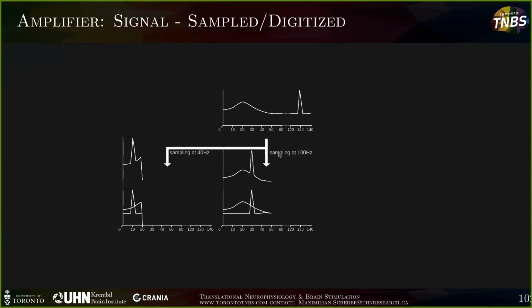So let's sample it at 100 Hertz, because we have a 20 Hertz peak, and we are interested in 20 Hertz. So 100 Hertz is certainly higher than 20 Hertz, even higher than 80 Hertz. And that's going to introduce the same issue all over again, partially. We managed now to properly sample our 20 Hertz peak, but we still have the issue that we didn't properly sample our 130 Hertz artifact. The thing now sits at 30 Hertz. And if it sits at 30 Hertz, it's significantly going to impact our analysis of, in this case, whatever happens at beta and gamma frequency.